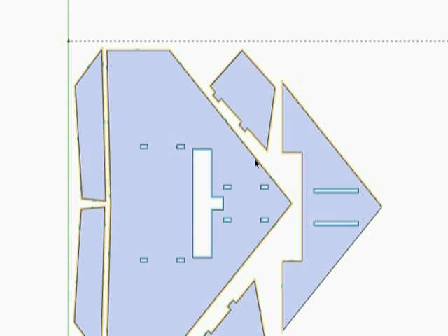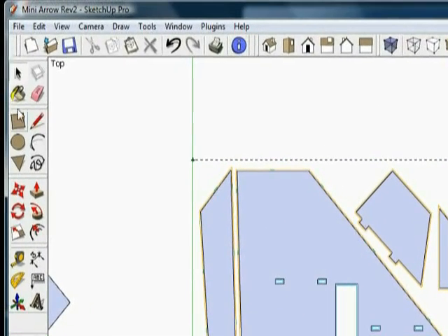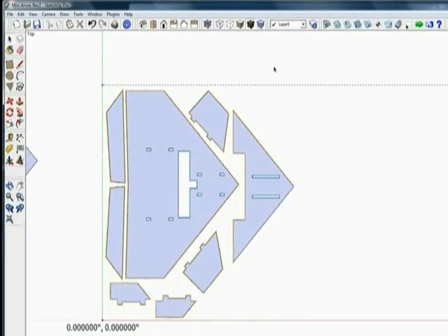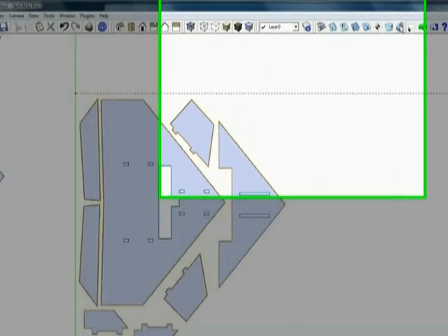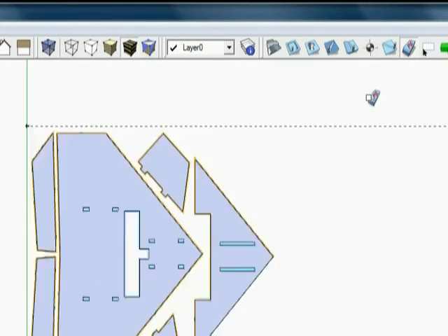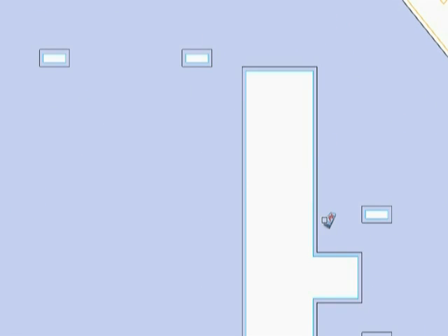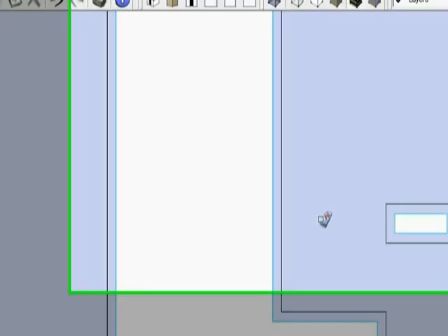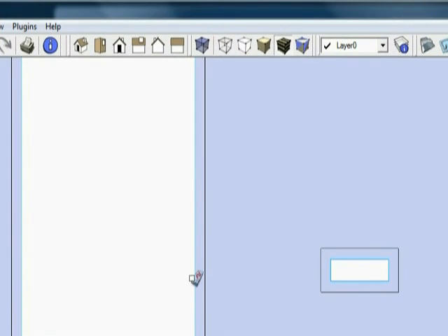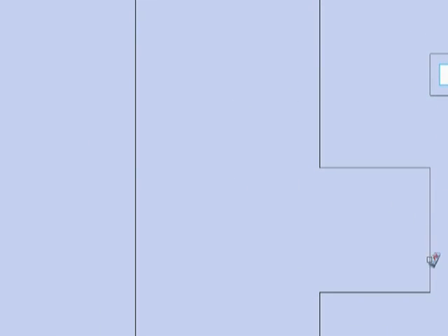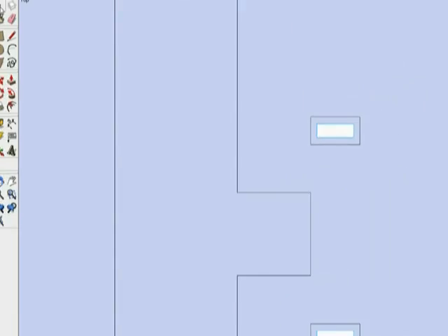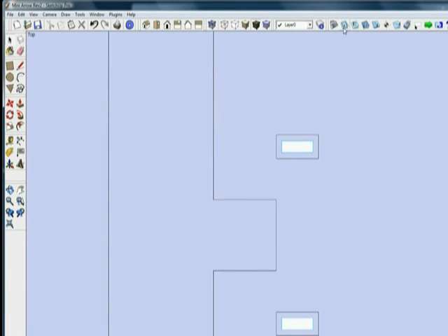Now, I didn't do all the rest of these parts. I don't think it's necessary. But there are some other features of the PhlatScript that we'll talk about. Real quick, let's talk about the eraser tool. This allows us to erase any flat edge that we maybe have a problem with. Let's say I want to redo this one. Well, I can click on that, and that entire element is gone. It allows me to go in and redo it, maybe if I had a mistake.